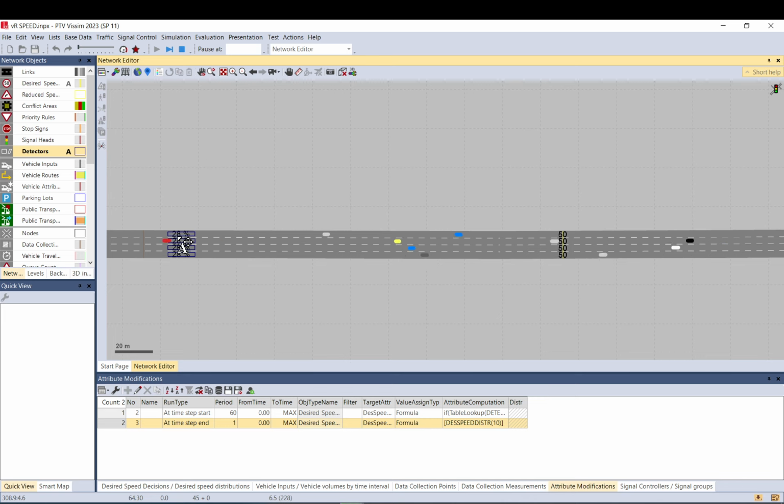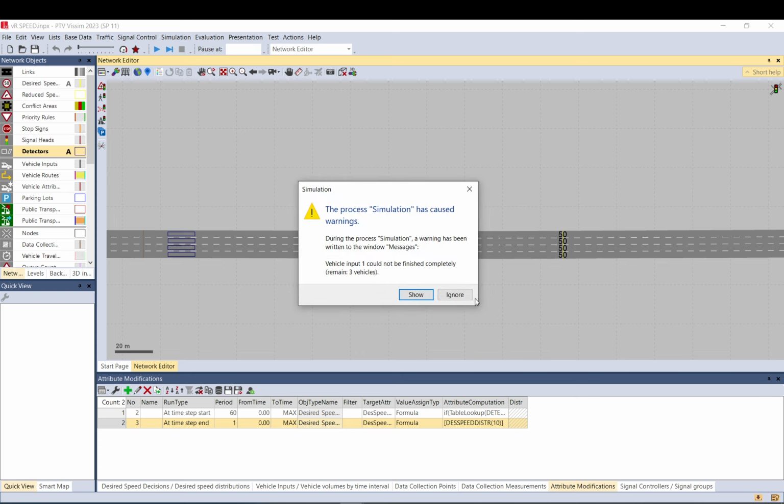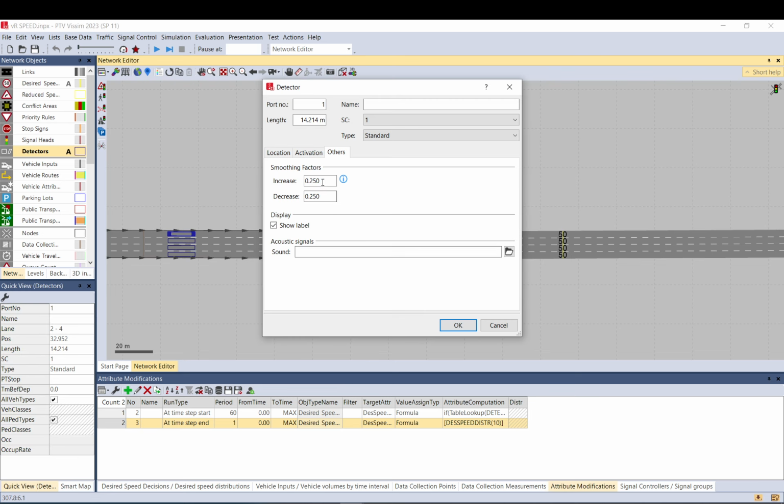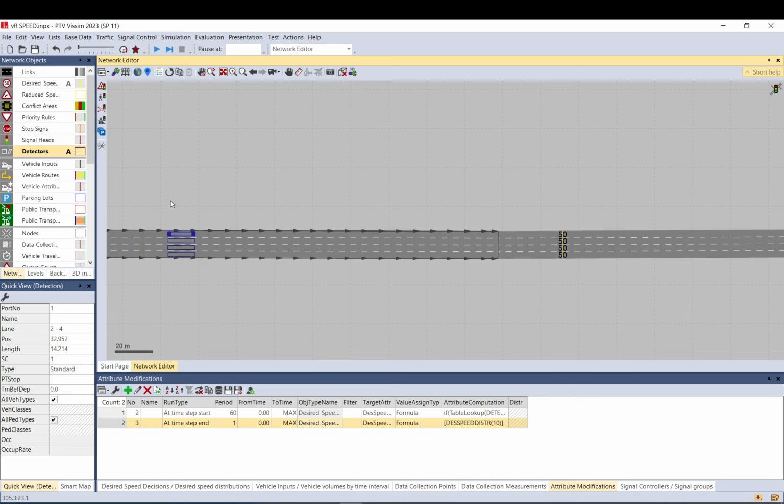You see it runs up, then it goes back, it goes up, it goes back. So it's not really suitable. But now you can see the change, 40, 50, 60, 50, 40, 60. So it's not really useful. So the smaller value you use as a smoothing factor, the slower the change will be. So maybe if you use 0.1 only, then the change will be longer, so it will be more like an average. As you saw before, it was moving between 60 and 70%. So I think a quite small number is more suitable for this application.